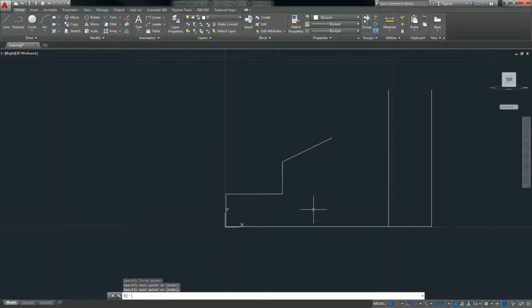what your preference is. So now I know that this line here is going to go back to right here. And my last offset is 68, so half of 68 is 34, so I'll offset 34. And then I'll draw in my line from here to here. I can now get rid of this, and draw my line in for this. And here I have my outside profile.